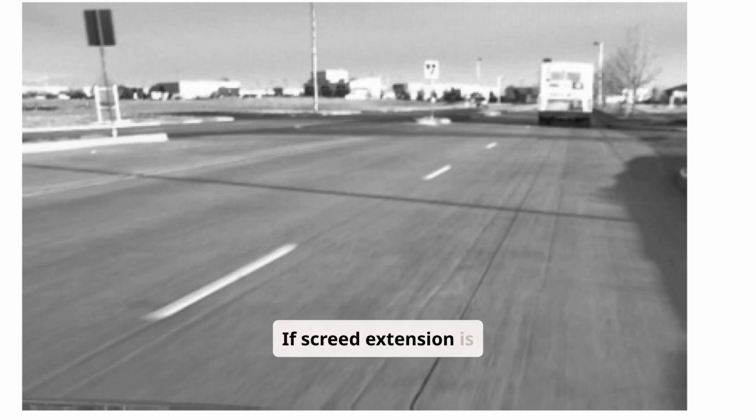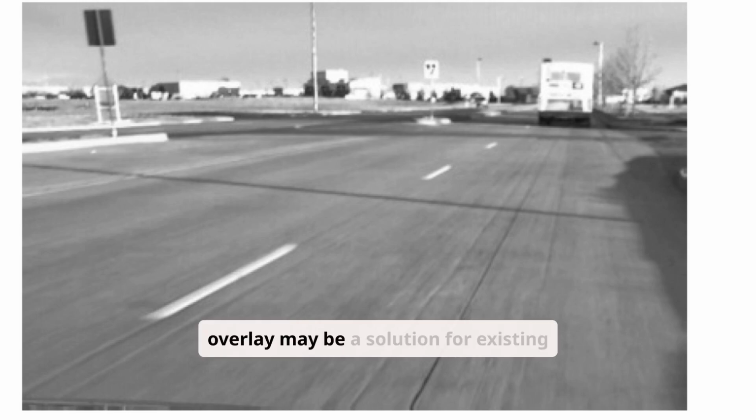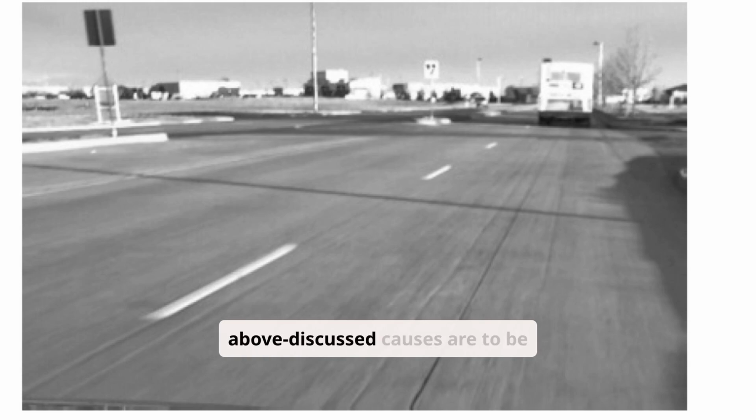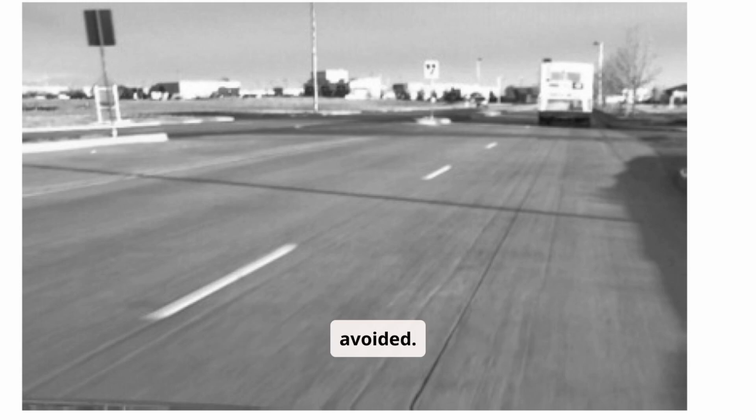If the screed extension is not properly installed for its crown and elevation, it could create a small streak at the point of transition from screed to extension. High paver speed can stimulate small aggregate particle disturbances to the point where the result becomes a visible streak. Stacked aggregates caught between the screed and the surface being paved may roll or be dragged forward. Chip seal or thin overlay may be a solution for existing mat tearing. To avoid mat tearing, the above-discussed causes are to be avoided.